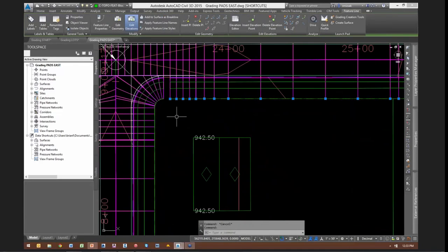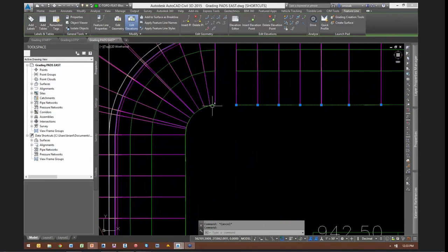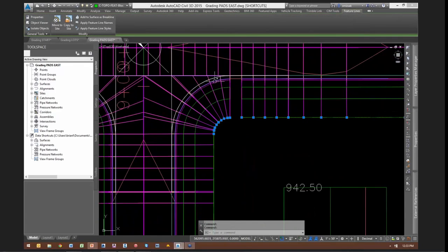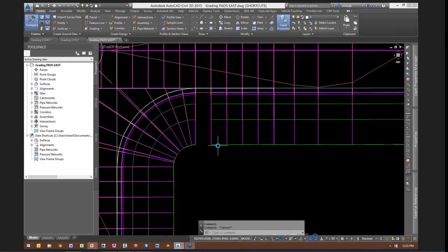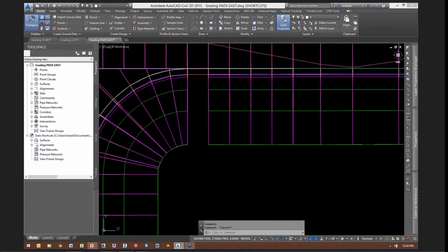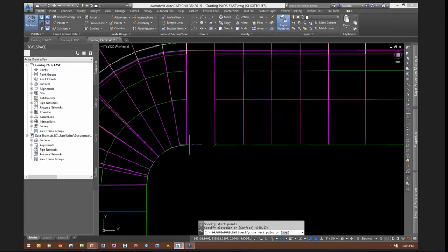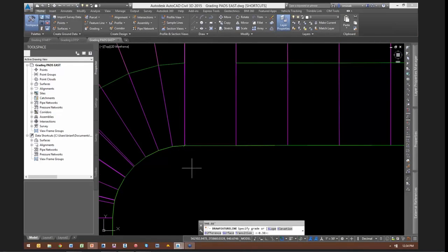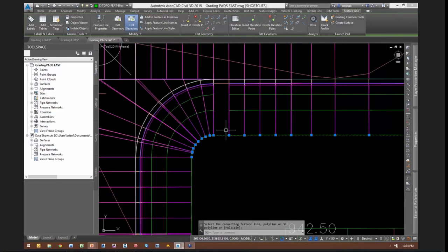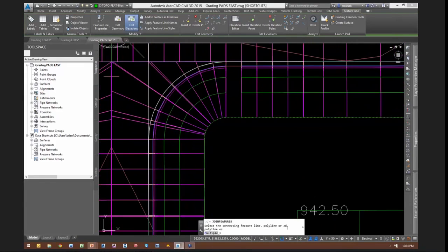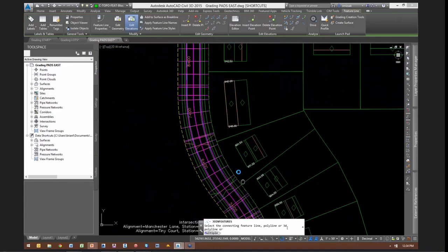And then what you're going to notice is that some of these don't touch. Occasionally the intersection tool, this is the way it builds. It's contouring fine in there. What we end up having to do is just add a couple extra pieces in here. In this case, I'm just going to draw a feature line manually, connect these two points. Then I can start joining these. So join that one to that one. Keep joining these all the way around here.